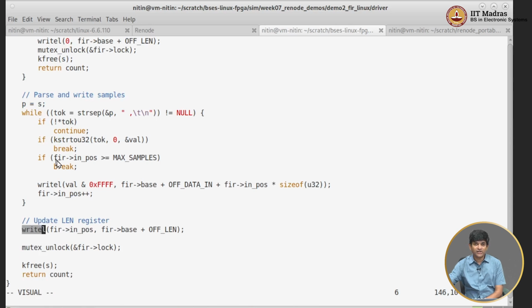So as far as the driver is concerned, the approach that we have taken is I don't want to directly go in there and modify the length register from Linux, but if I keep on writing data into that data in attribute, it will keep track of what the present length is and keep on increasing that. This is actually an interesting way of doing things, as we will see in a moment when we run it.